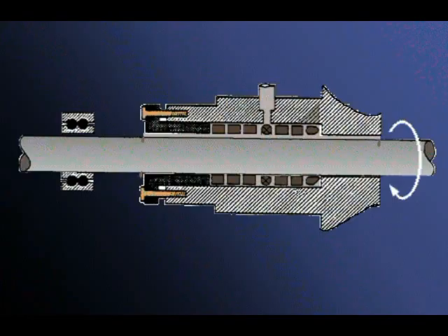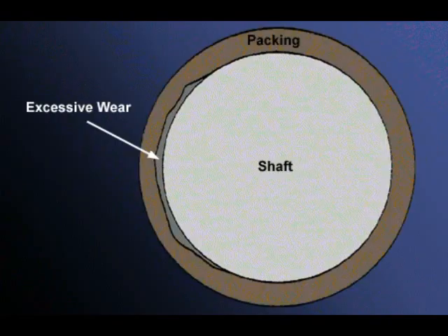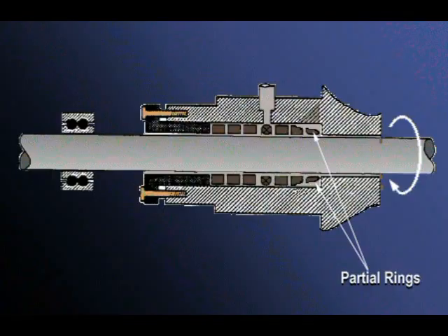Problem: excessive reduction in cross-section of packing directly below the shaft. Possible trouble: shaft riding on packing. In service, early leakage occurs around the top of the shaft. Problem: excessive wear of packing directly over or on either side of the shaft. Possible trouble: shaft out of alignment, causing badly worn bearings and whipping of the shaft. Problem: part of one or more rings is missing from the set. Possible trouble: bottom of the stuffing box is badly worn, with packing being extruded into the system.